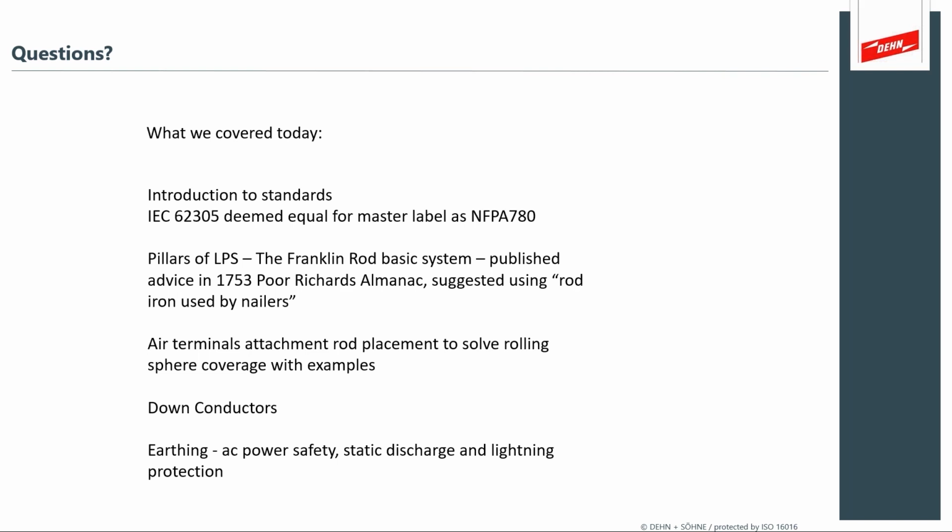So the standard, I've never seen anything that looks like a target value to put a clamp-on meter and say, okay, I see 1 ohm. I've never seen necessarily something that looks like a target value like that. But in practice, we see stuff that looks like tenths of an ohm.